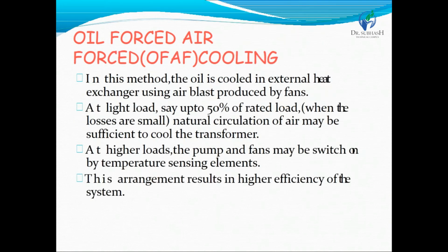Now the next topic is oil forced air forced cooling. This type of cooling is preferred for transformer ratings above 60 MVA. This type of cooling is used as shown in the previous slide figure. The separate cooler is mounted away from the transformer tank, as shown in the next slide figure.